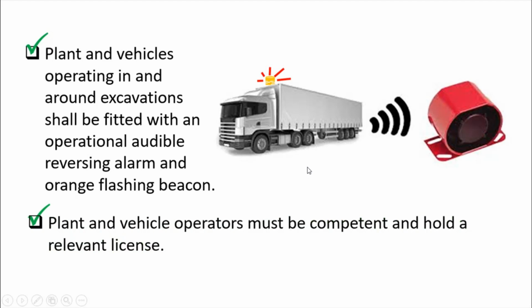Plant and vehicle operators must be competent and hold a relevant license. There are so many incidents happening because of lapses of the operators when they are reversing to the excavation to bring materials beside the excavation. The excavation collapses or the truck falls into the excavation because they are incompetent for that activity.